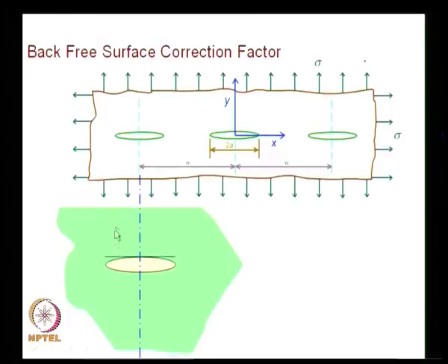See, the edge becomes free, there is no constraint that this slope has to remain horizontal. So, in essence the crack will open up further, that is what is shown here. The slope need not remain horizontal and the crack will open up. So, for the crack to open up, you need to apply more stress.